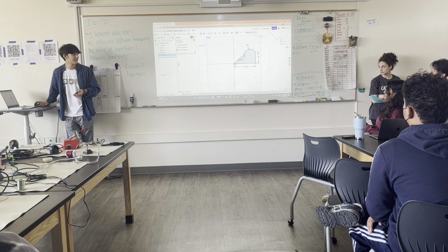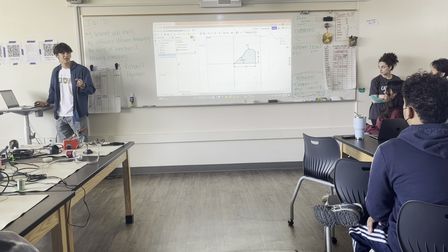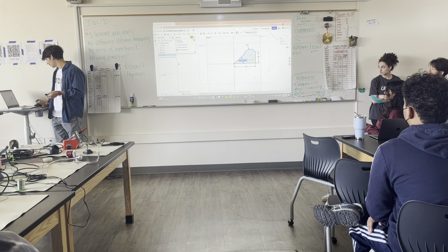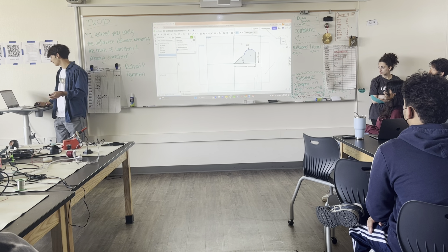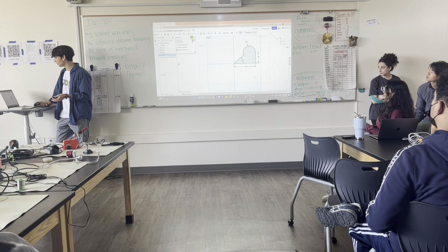Another thing is to define angles, for this angled piece, you can do it by length, but you should also know that you can do angles by clicking between two lines like this. Now I'm going to use a relationship to define the rest of this. I can click this one and this one. Not coincident, sorry. Horizontal. So make those two horizontal.